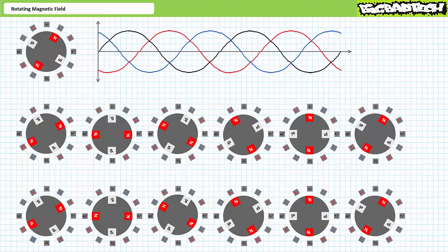Operated at 60 Hz, this means a full revolution takes 2 times 16.7 milliseconds, or roughly 33.3 milliseconds. If we stood here for a full minute, or 60 seconds, we'd observe 60 seconds divided by 33.3 milliseconds per revolution, or 1800 RPM.